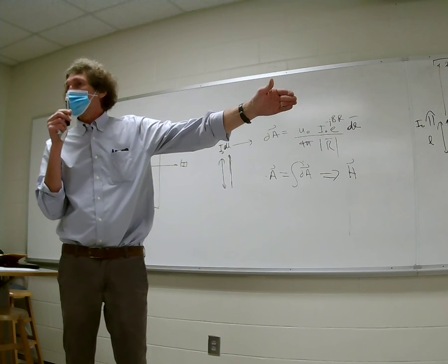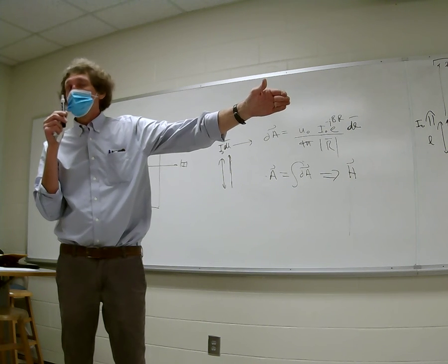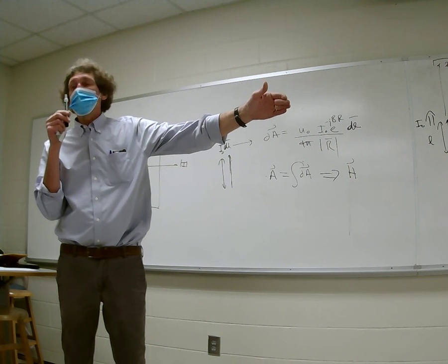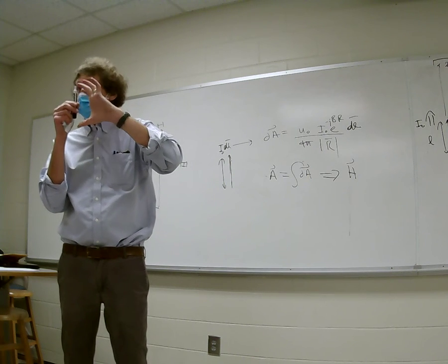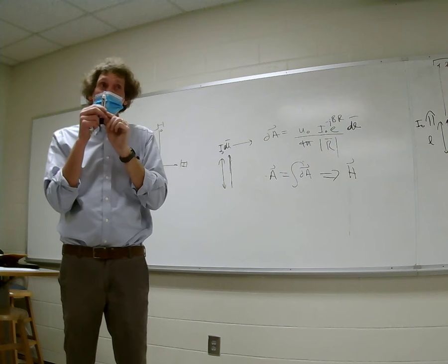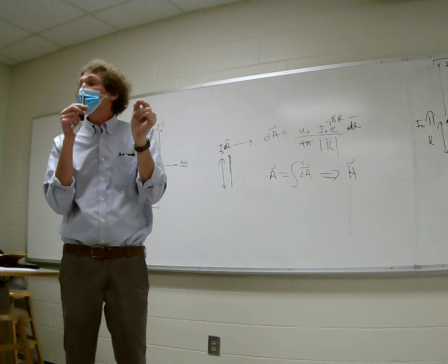Keep going in frequency though. Instead of having 300 megahertz, make it 3 gigahertz. Now what's the wavelength? It's not 1 meter, it's 10 centimeters, isn't it? Now the antenna becomes a large fraction of the length of the wavelength. You with me? Now my analysis doesn't hold true, and also the far field would be a tenth of a wavelength. I mean, sorry, 10 centimeters away.